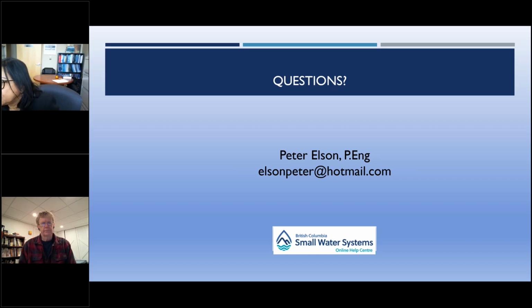Next question, Peter: do SCADA systems require scheduled regular maintenance, and would that be covered by Indigenous Services Canada funding for the First Nations communities? Yeah, with SCADA systems, it's more a matter of maintaining your sensors. If you've got a chlorine sensor, pH, anything like that, that has to be calibrated on a regular basis, but that should be covered from your maintenance funding.